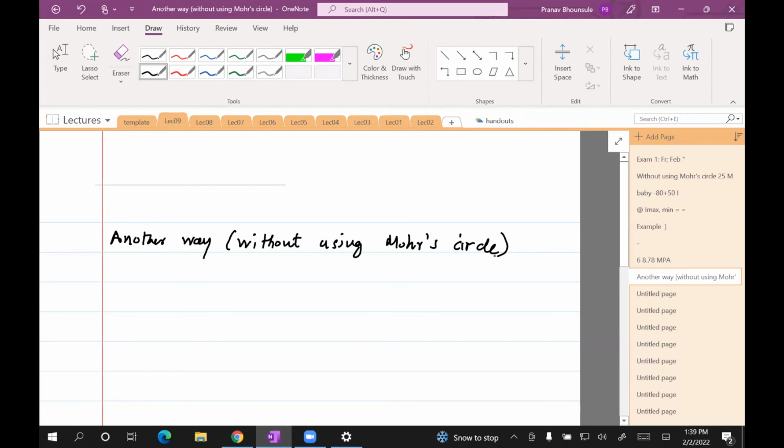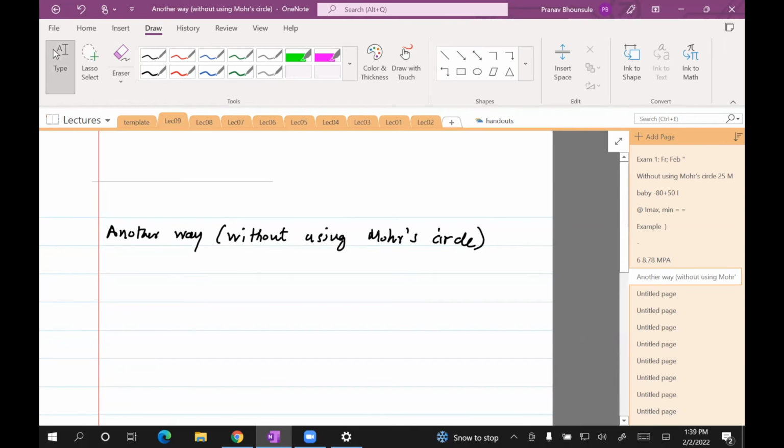Okay, so if you turn the pages, you see the formula I wrote down for transformation of stresses. So if given the stresses for the plane stress element, then you can find the stress at an angle theta. That is sigma for the stress normal and tau for the stress along the plane, given sigma x, sigma y, tau xy.